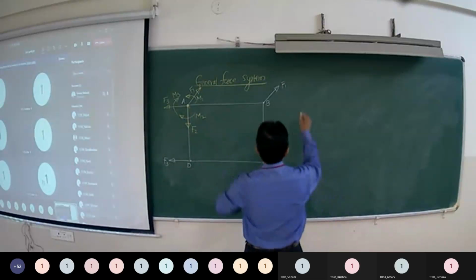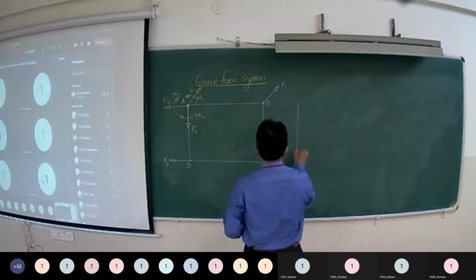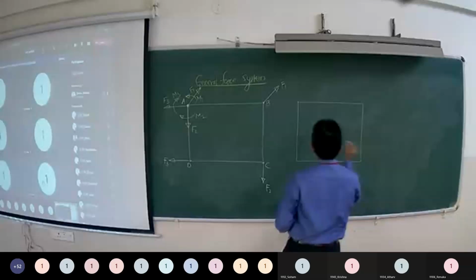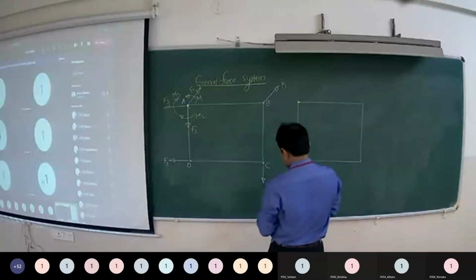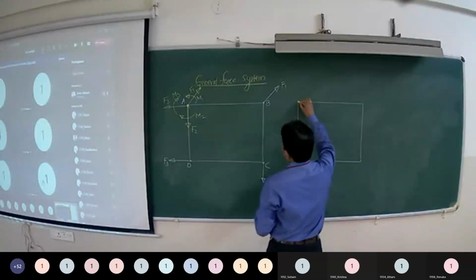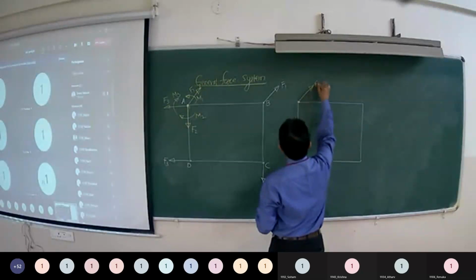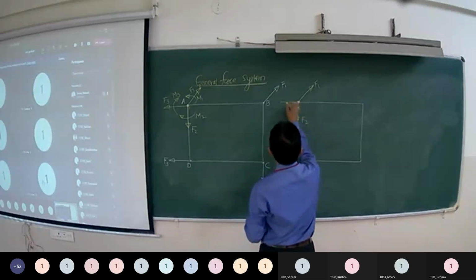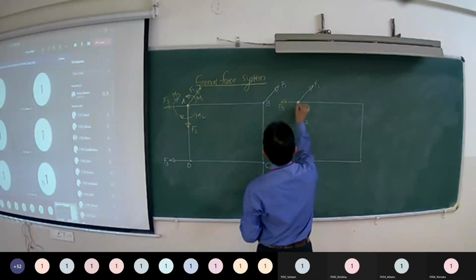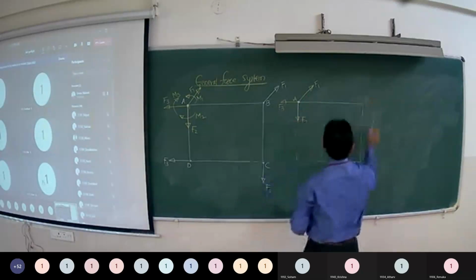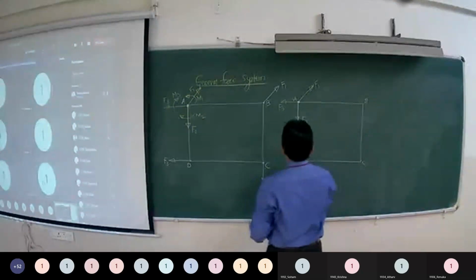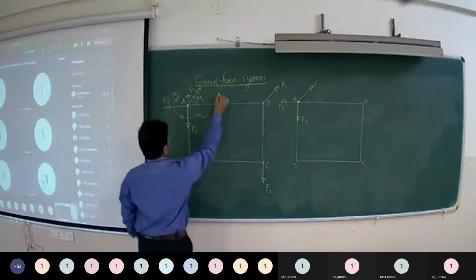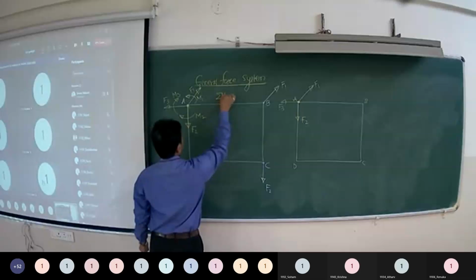That means now the given system is reduced to a simple system with concurrent forces at point A, say F1, F2, F3, along with a resultant moment. So from this M1, M2, M3, you can find out the resultant moment taking algebraic sum.